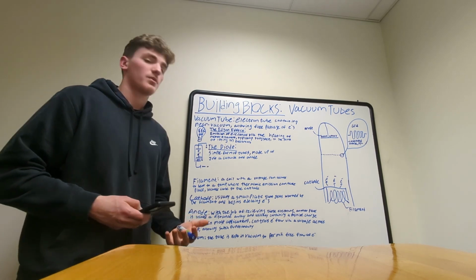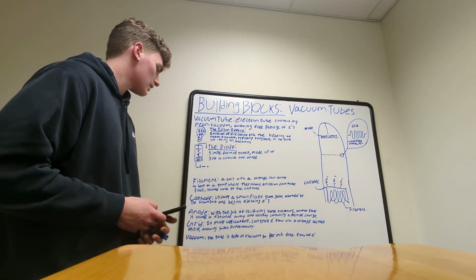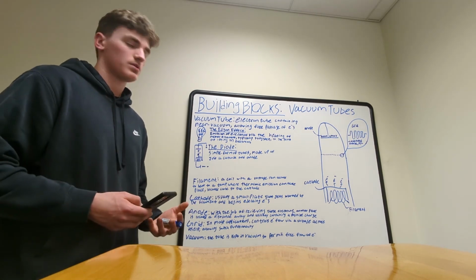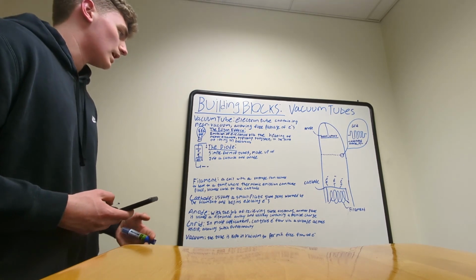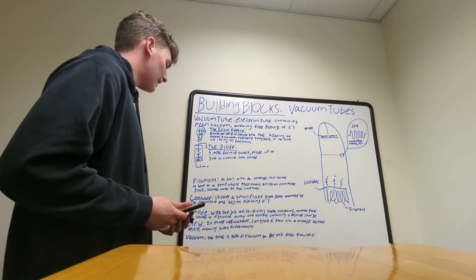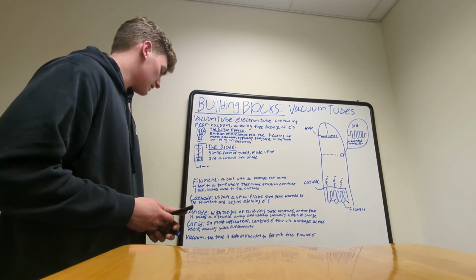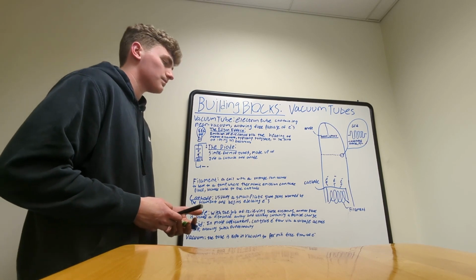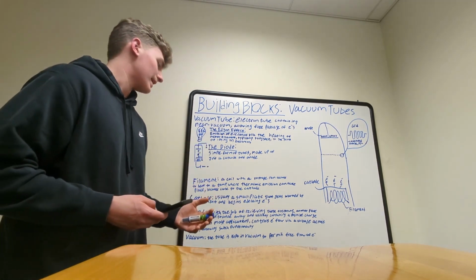This set temperature is where thermionic emission is capable of taking place, given what kind of metal we're using, and the filament is located relatively near the cathode in order to emit that heat onto it. Now this cathode is just a small plate. It gets warmed by the filament, and it's capable of beginning to emit these electrons. Above that, we're going to have something called an anode. This just has the job of receiving these electrons. It's just another plate located a distance away, and typically contains a positive charge in order to facilitate the flow of these electrons across the space between the cathode and anode.